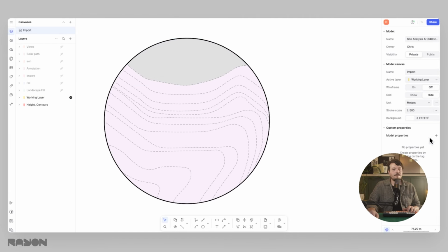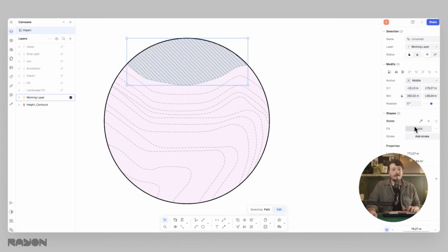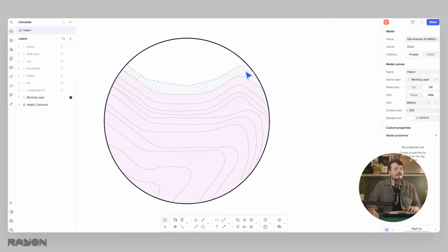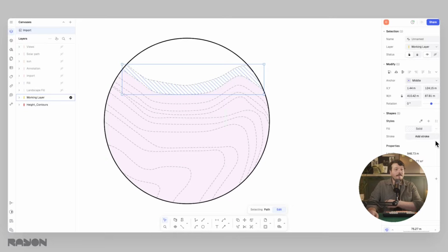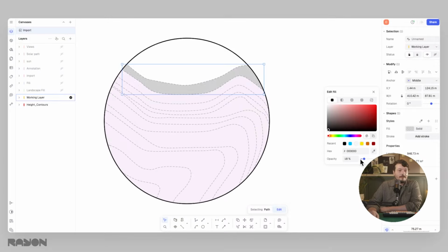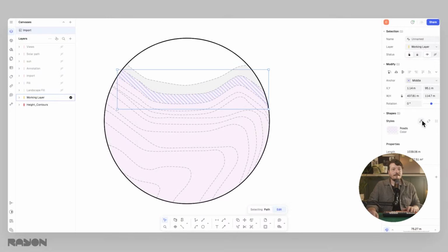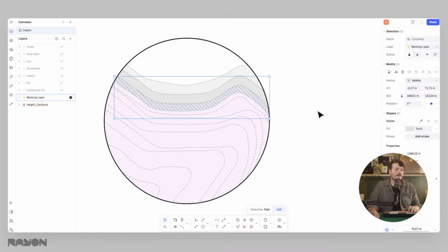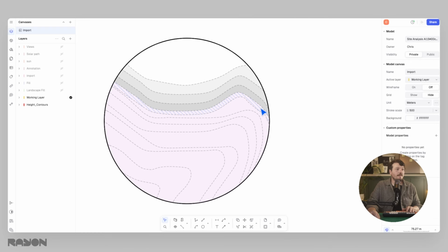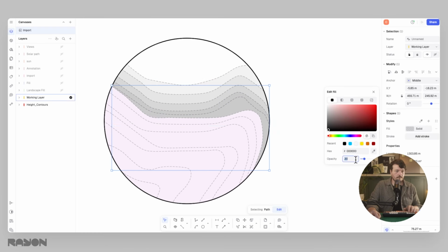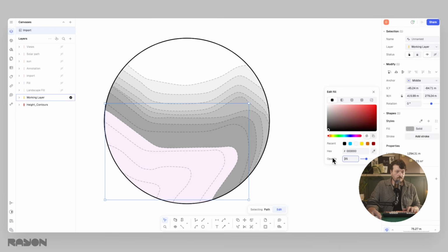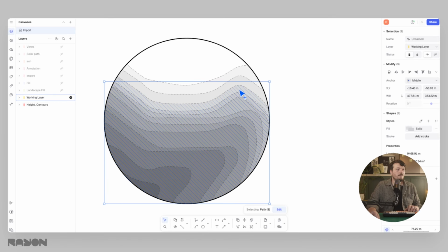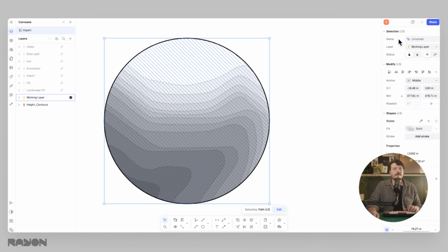We'll call this contours. So this would be our lightest. So we'll say this is at 0 fill. And then we'll say at every layer that we go down, we'll add 5% maybe. Let's see how that gets on. So the next contour is then 10. The next is 15. And then so on. There we go. So let's make sure all of those are selected.